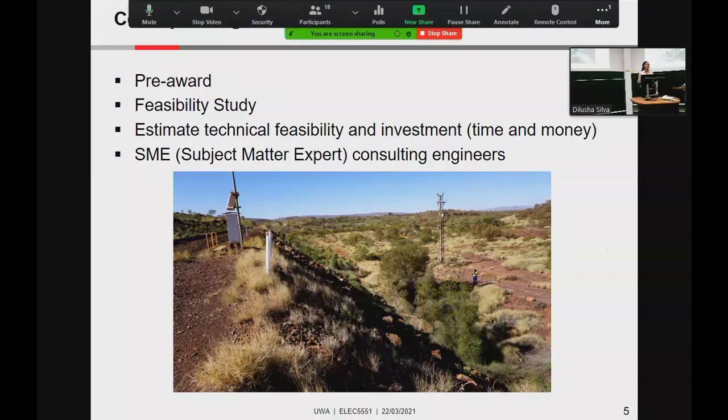Eventually, what looked like a good solution, even though expensive, was let's put everything on fiber. It's like, okay, it's only 500 kilometers this way, 500 that way, no problem. We'll do the feasibility. So we did a feasibility. There'll be a mainline fiber parallel to the train track, and we'll decommission all these radios, connect all these little asset protection telemetry sites to the fiber, and then that's it, problem solved for good.